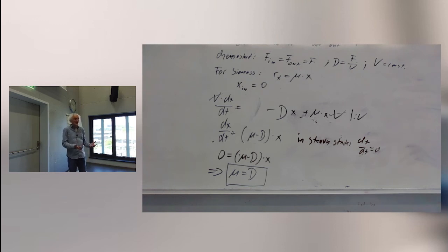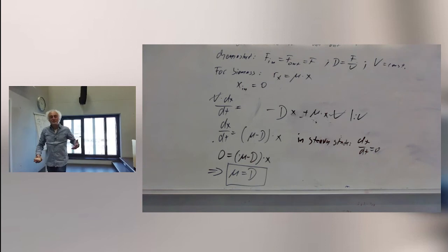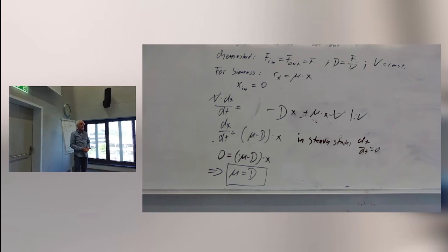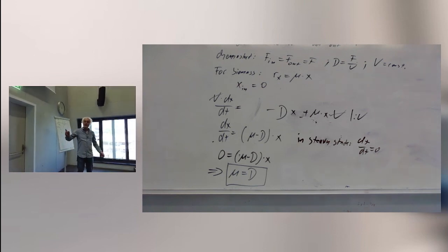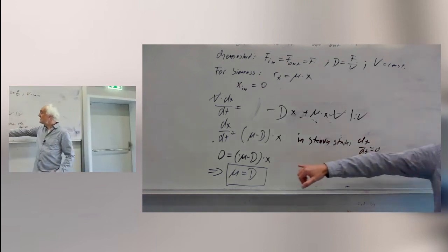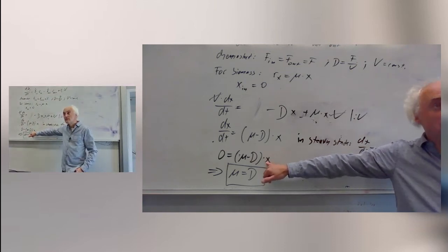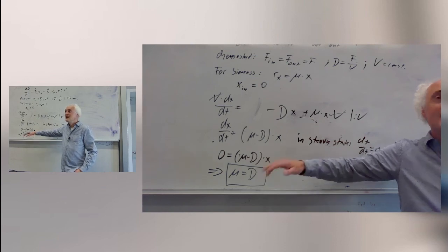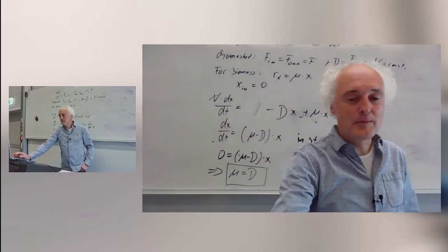If I would increase the dilution rate further, it's yeast, and yeast will not be able to grow faster than a certain maximal specific growth rate. For yeast, for example, the limit is 0.4 per hour. And if I would set a dilution rate of 2 per hour, this is too high. What will happen? I will simply wash out the yeast. Then the other stable steady state will be achieved, x equals 0. This is very stable if no biomass is inside. But this is, of course, not something where your boss will be happy with you. So this is the chemostat experiment.